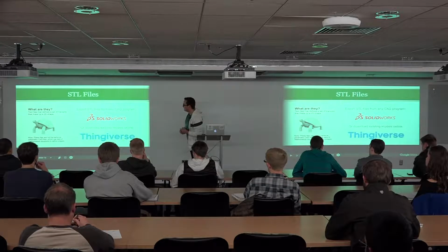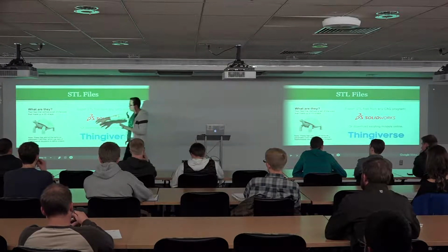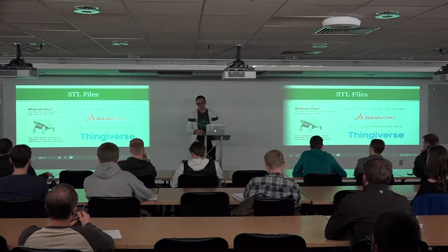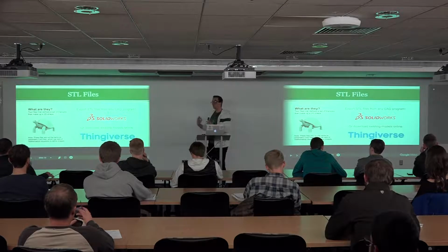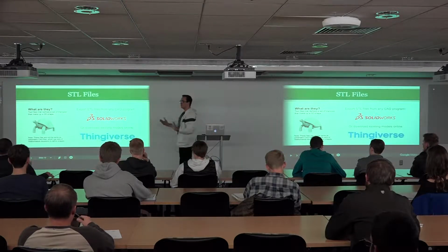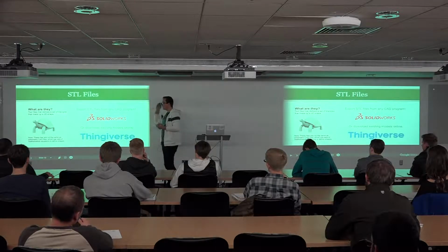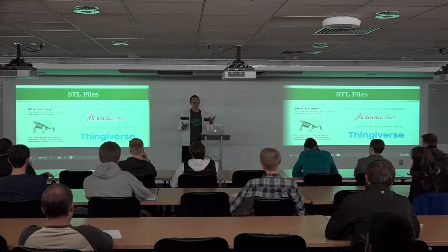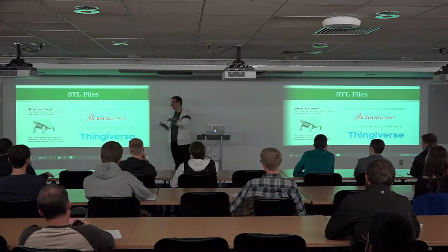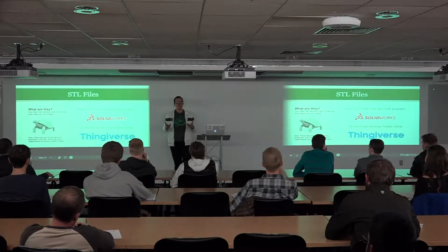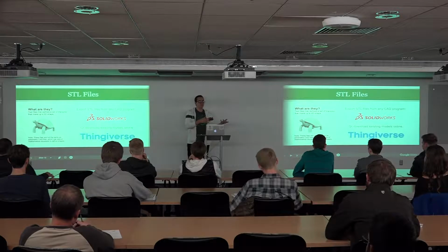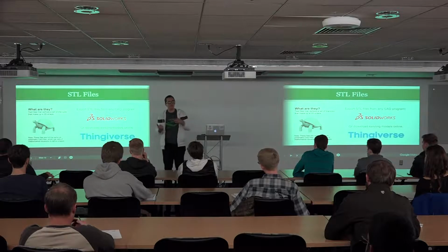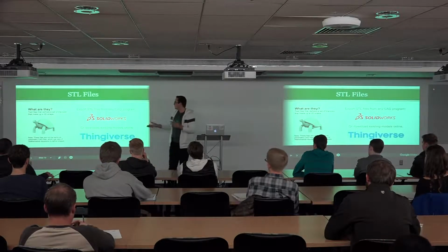Because of that, they're not the same as a regular CAD file. They don't have perfect circles and curves and things like that. So if you get an STL file and you want to edit it in SolidWorks, you have to go through some conversion. We do have software that makes that possible, but it's not always perfect. It's kind of like if you're familiar with doing vector art in Adobe Illustrator, and you can convert that to a JPEG file and use it in Photoshop. But going back the other way is a little bit harder. So it's kind of the same as that.